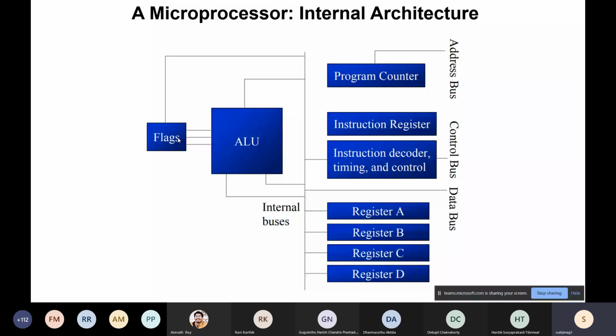So without looking at the actual value of the result, let's say after addition you are getting some value where all the bits are 0 or all the bits are 1. Instead of reading all 8 bits together, or 1 byte together, just looking at 1 bit in the flag through another line of code, obviously, you can determine what the previous result was. The opposite is also possible.